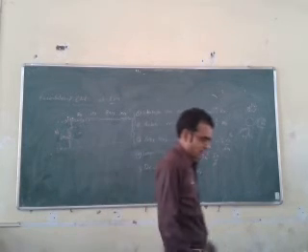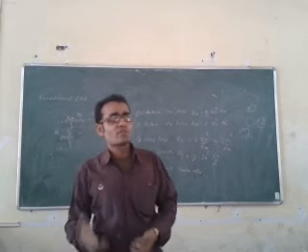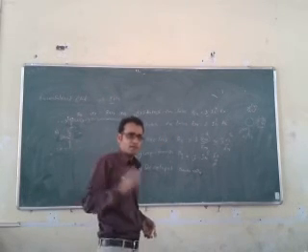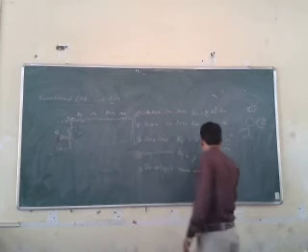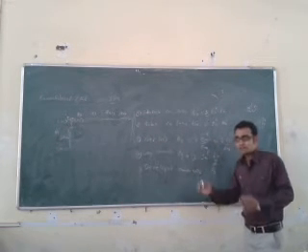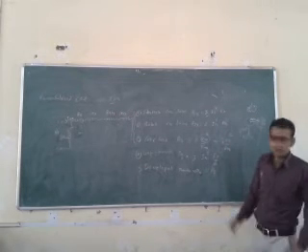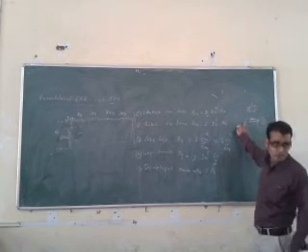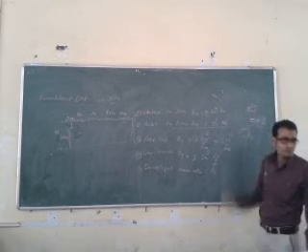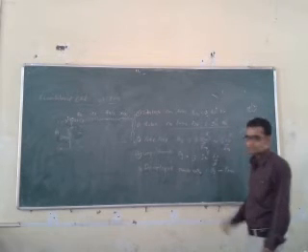So this developed power PD is equal to the power transferred from stator to the rotor minus the losses generated by the rotor. Very simple. So the power transferred from stator to the rotor is equal to PG, which is gap power. This much power is transferred from stator to the rotor. Then there may be some losses. We have to deduct this. These losses are rotor components. So you can say, PG minus PR.